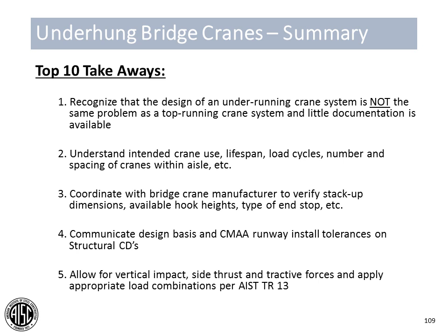Make sure you coordinate with the bridge crane manufacturer, if at all possible, to verify the stack-up dimensions for clearances, available hook heights, type of end stop, etc. If you can't communicate or coordinate with them early on in the project, make sure you communicate your design basis as well as those CMAA runway installation tolerances on your construction documents. Allow for all of the impact forces as well as the load combinations per AIST Tech Report 13 or your interview with your client early on in the project.